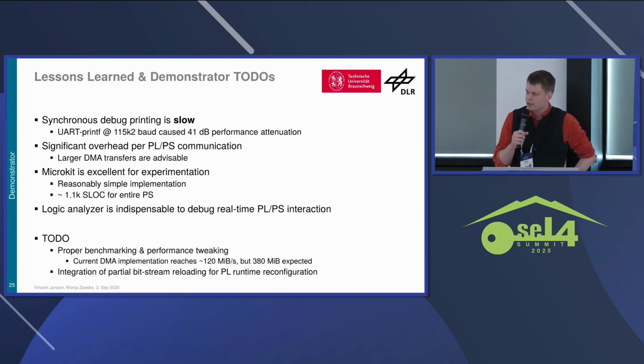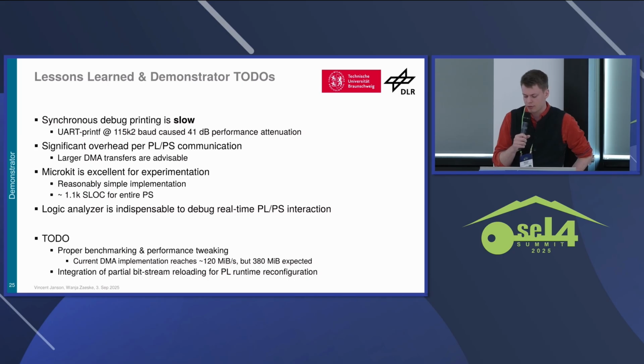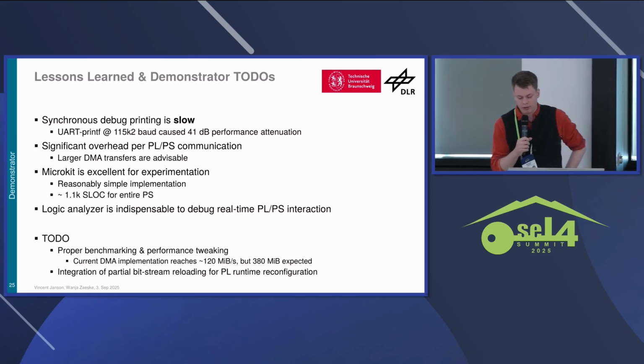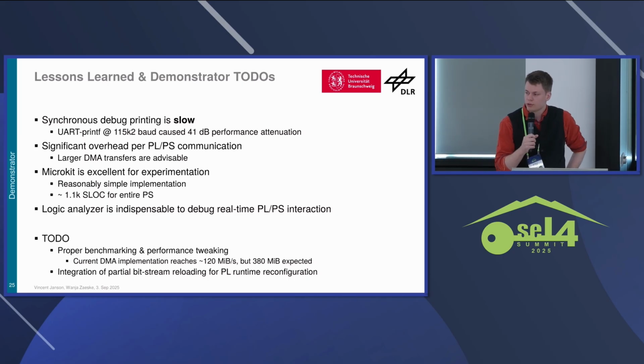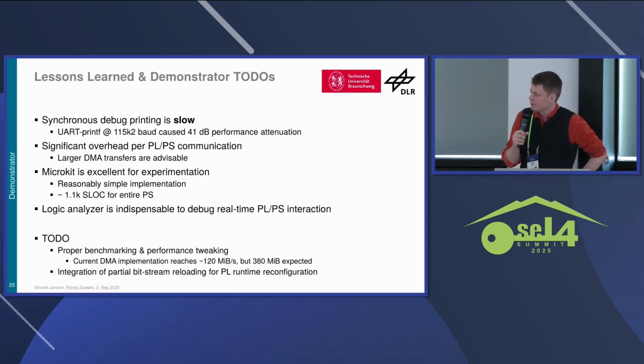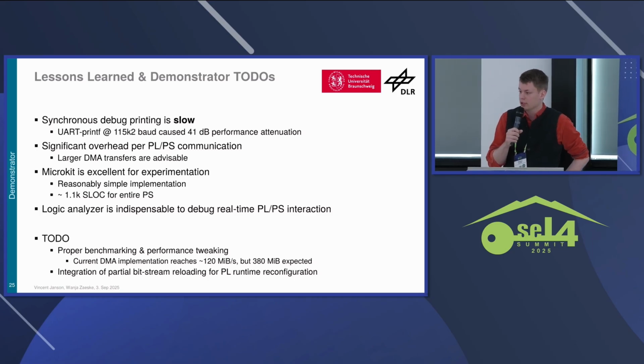In total, the PS side of this also is quite small in code, about 1,000 lines of C. So this was really, really working well. Last but not least, whoever wants to attempt something like this, buy a good logic analyzer. You will need it.